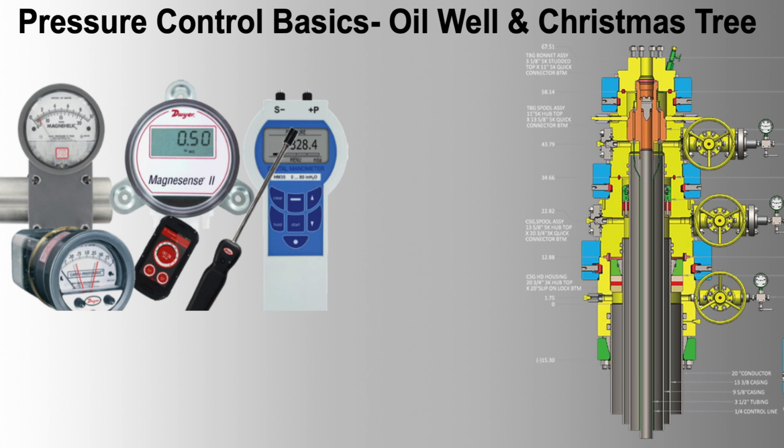4. Other criteria. Redundancy. Implement redundant pressure measurement points for critical applications to enhance reliability. Signal output. Ensure compatibility with control systems, e.g. 4-20 mA HART, for seamless integration and data communication. Hazardous area certification. Select instruments certified for use in potentially explosive environments, e.g. ATEX, IECEx. Examples of pressure instrumentation design and selection.